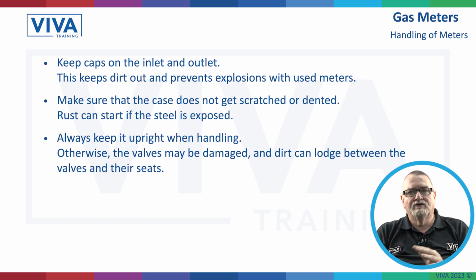The other thing is, if we don't do that, some of the older meters, they've got valves in there, and we can get dirt in the valves and we can cause them to stick and to lock up when we put them back. So when we're taking meters out, if we have to, we've got to treat them with care and treat them gently.